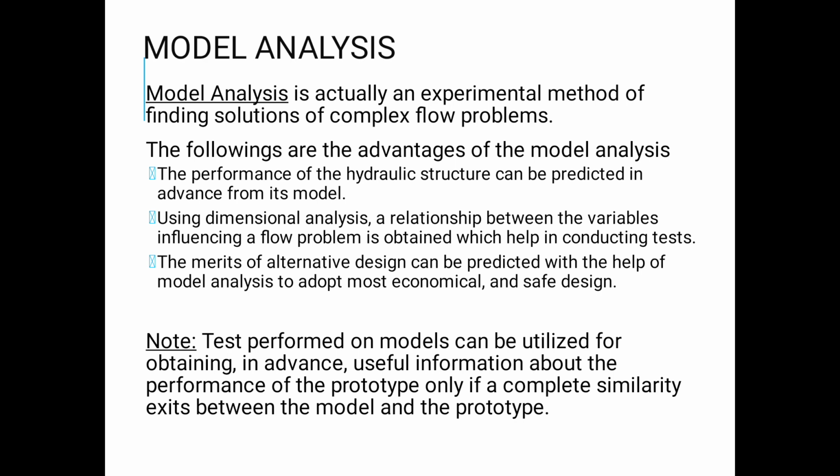The performance of a hydraulic structure can be predicted in advance from its model. Using dimensional analysis, a relation between the variables influencing a flow problem is obtained, which helps in conducting tests. The merits of alternative design can be predicted with the help of model analysis to adopt the most economical and safe design. Tests performed on models can be utilized for obtaining in advance useful information about the performance of the prototype only if a complete similarity exists between the model and the prototype.